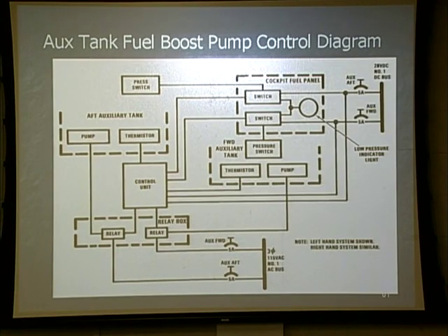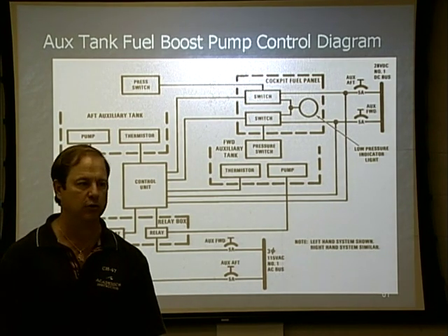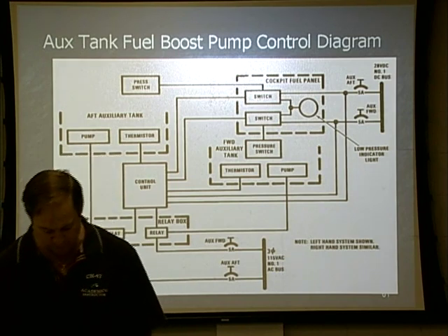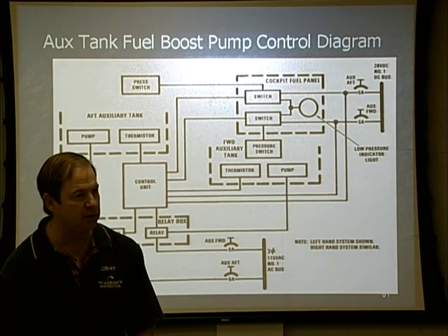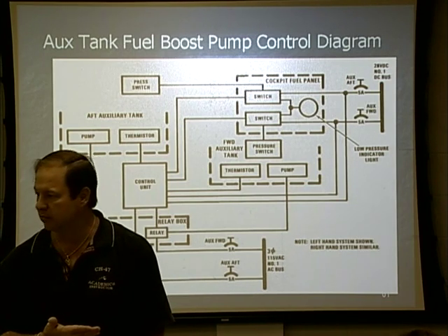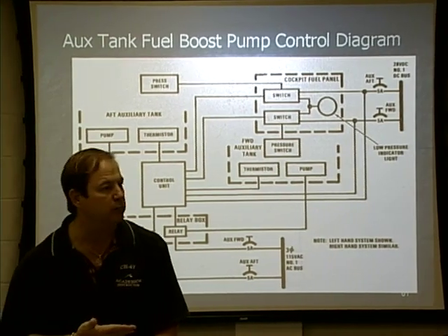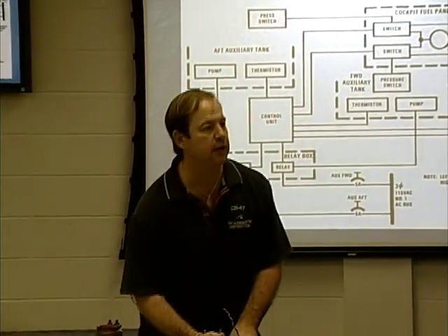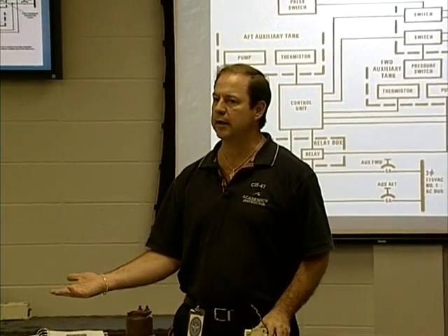Now, the aux tanks are a little bit more complicated in the fact that what? Not only do you require both AC and DC, but we also have to factor in these thermistors. Because what happens is with these thermistors, both the thermistors have to be covered to cool them down sufficiently to allow that pump to be activated, and they both have to be uncovered to heat them up to the point that it's going to shut it down.